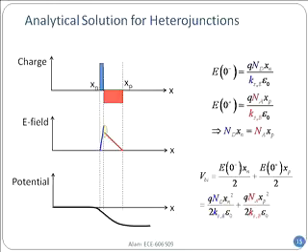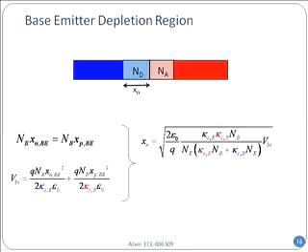So when you have VBI, then in order to have VBI, you have to have the area under those triangles for the electric field, right? For the blue line and the red line. Correspondingly, you have the electric field at 0 minus multiplied by xn, and the electric field at 0 plus multiplied by xp, divided by 2, is the triangle. And so you can insert the values of the electric field and get the expression for VBI. Two unknowns, two equations. Well, you have done it many times. You know how to do it.